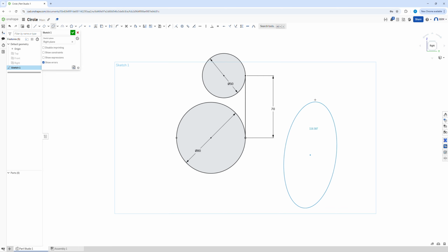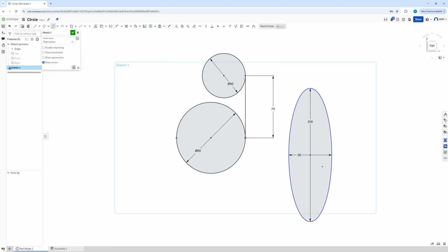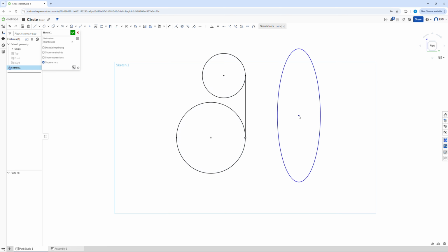Okay, so my long axis is going to say, let's make it vertical, and now we're affecting the short axis by moving the mouse side to side. So all I've done is I've clicked once, I'm not holding the mouse down at all. I can then click again, and you can see this is currently 146mm, so let's make it 150mm with its long axis by, let's say, 50mm with its shorter axis. Okay, it's obviously still all blue, so we can move it around anywhere.